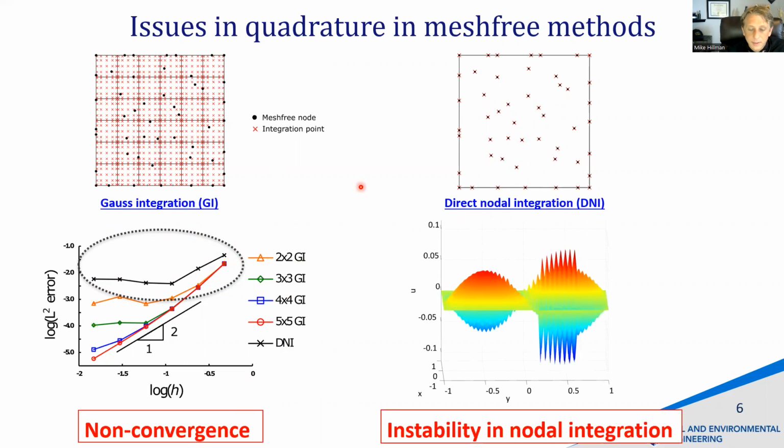Another thing that we'll have to take care of is instability. So you'll get these almost like hourglass modes in FEM, where you're getting node-to-node oscillations in your solution. You can see very clear for this Poisson equation showing up here, where I should just get a very smooth solution, but getting these spurious node-to-node oscillations. So we'll see about stabilizing those. And again, trying to fix these two issues with particular emphasis on the coupled problem.